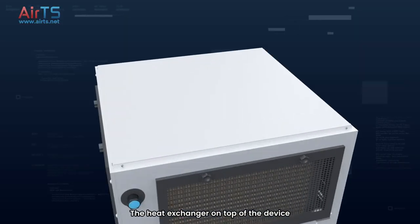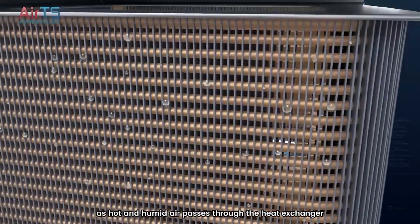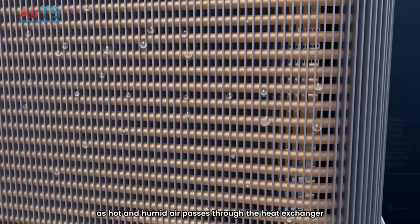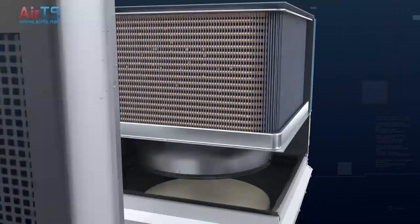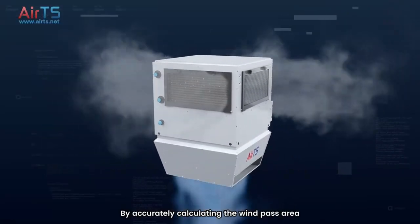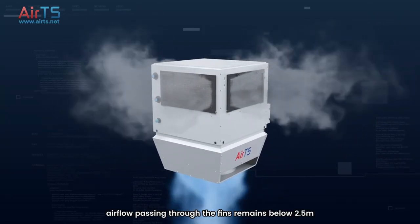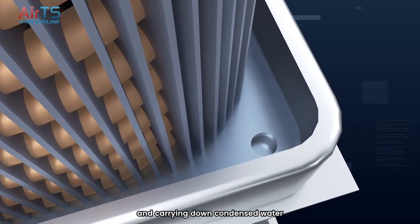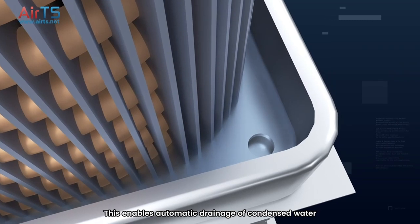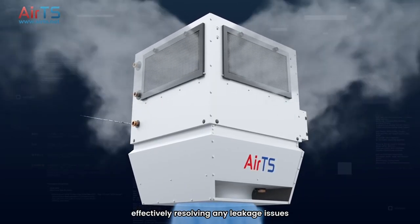The heat exchanger on top of the device utilizes our company's patented mouth-shaped coil design. As hot and humid air passes through the heat exchanger, condensed water adheres to the vertically positioned aluminum foil fins. By accurately calculating the wind pass area, even at maximum wind speed, airflow passing through the fins remains below 2.5 meters per second, preventing it from overcoming gravity and carrying down condensed water. This enables automatic drainage of condensed water into a tray under the heat exchanger, effectively resolving any leakage issues.